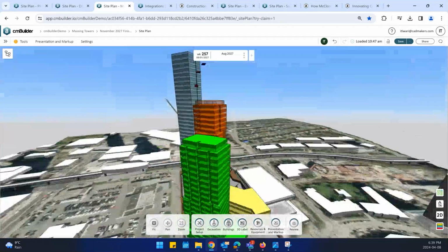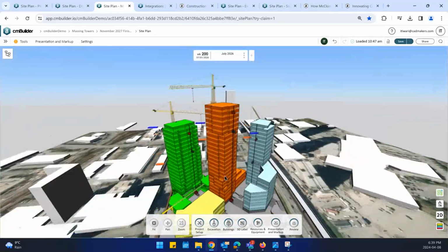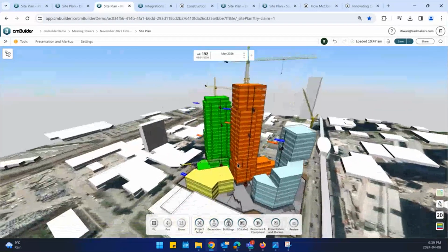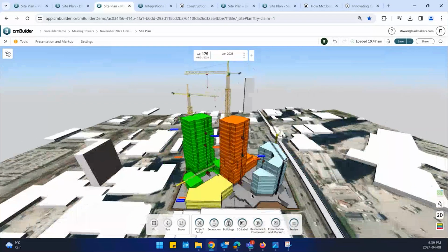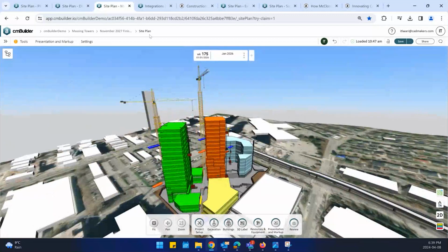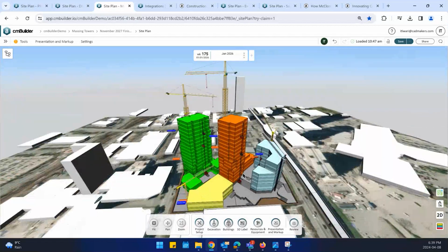You can always use the massing tool to quickly mass out a volume of your building and still be able to place the cranes and the hoist in the right position, plan those out, and do everything I showed today. You can share a video out of this as well. So having a 3D model is great and always helpful, but you can also use massing as an example.